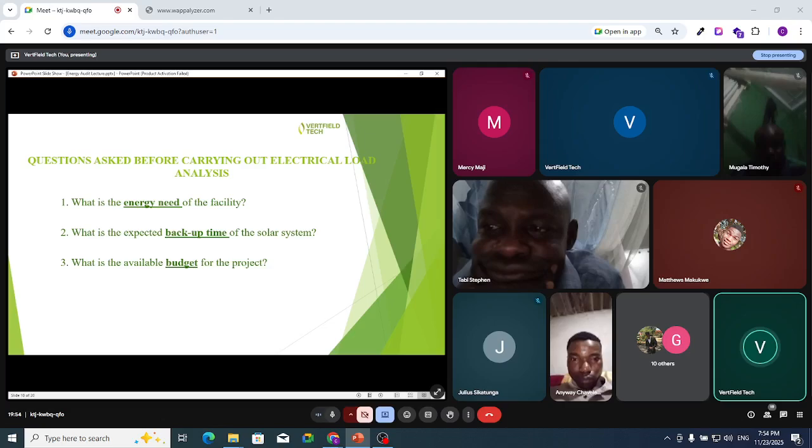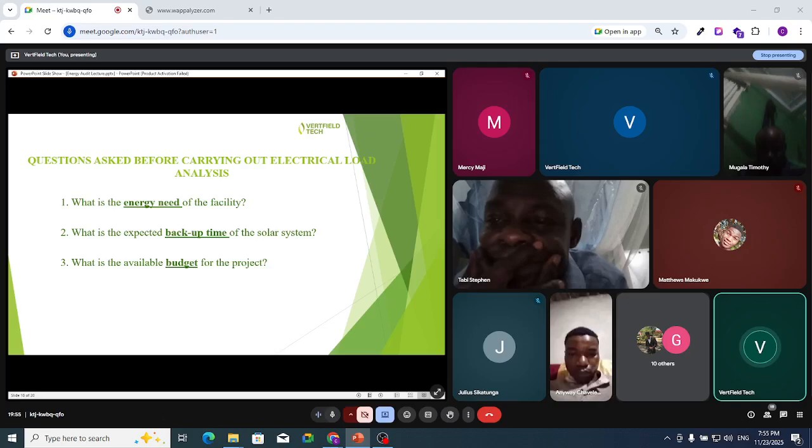What we'll definitely do is to talk to Mr. Steven, let us give you something within the price range of 5,000 so that he can be able to at least have electricity in his facility at that point in time and then prepare for upgrade. So 3 important questions to ask. 1, the energy need. 2, the backup time. And 3, the available budget.